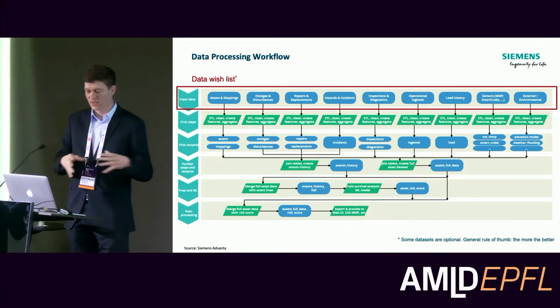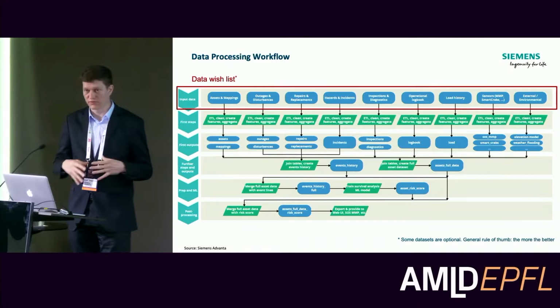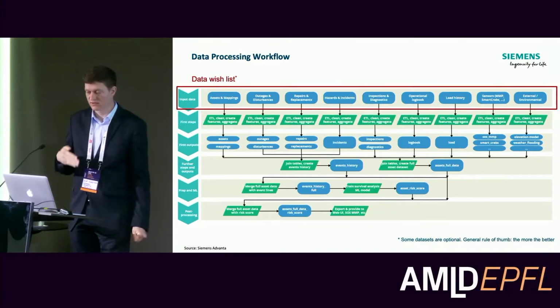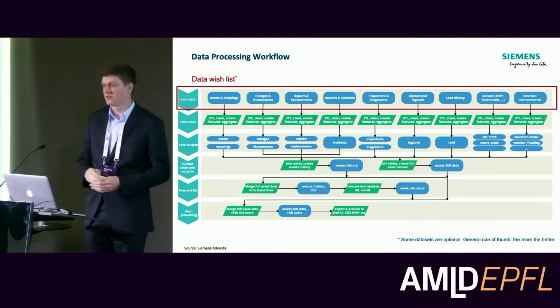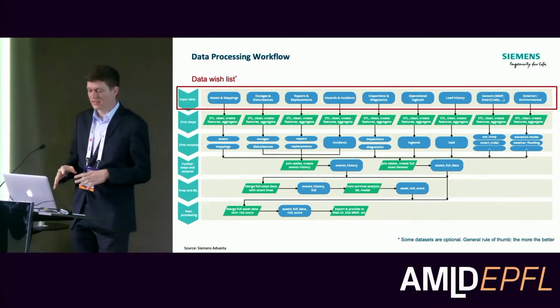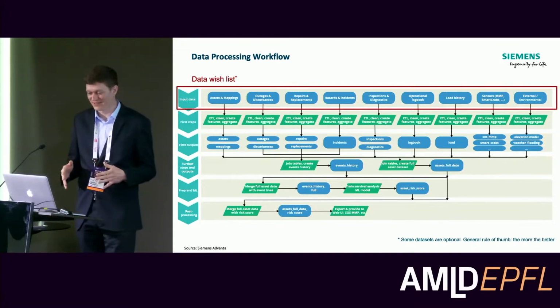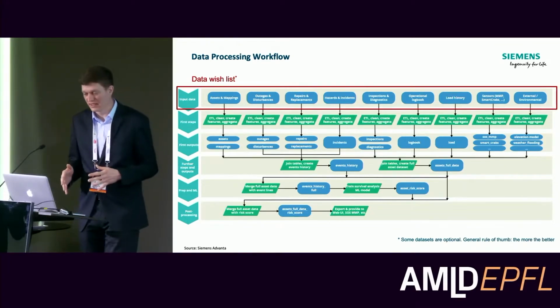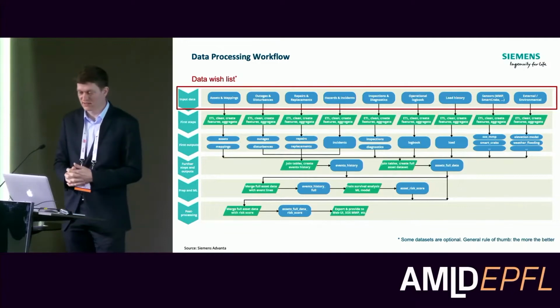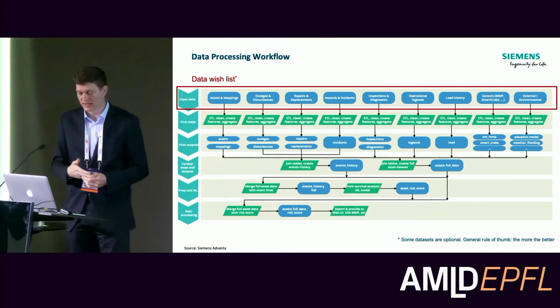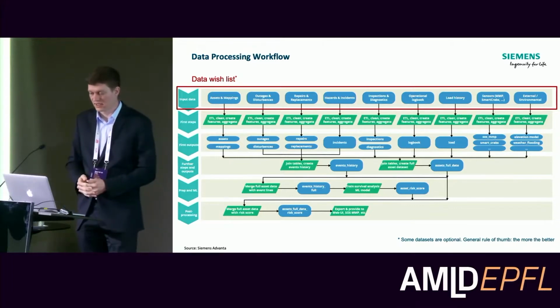You might need to take a model from another grid and use transfer learning. Then also repair and replacement activity, so you always update the asset status. And that's basically what you need as a basic data set. And then in industry, it depends what else you can get with a reasonable effort. For instance, diagnostics measurements are typically no problem if they have diagnostics and they can easily map them to the cables.